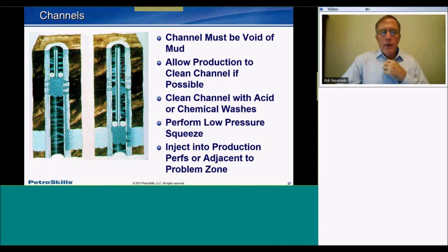The second option is to do a circulation squeeze. So what we do is we go down into the unwanted production interval, the water, we perforate, and we establish an injection rate back into the producing holes above, and we circulate cement through the channel from below back into the casing. Now, a couple things to be aware of here is that if we're going to perforate with the intent of filling this channel from below, then we have to have a pretty good level of confidence that wherever we perforate is going to intersect the channel. So you might want to think about that, and then if you decide to go this route, how are you going to orient your perforations around the casing to make sure that you give yourself the best chance of success.